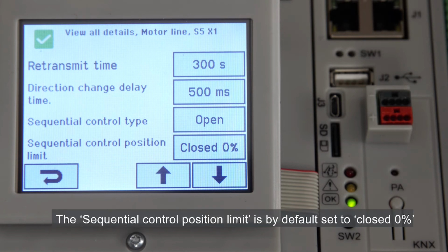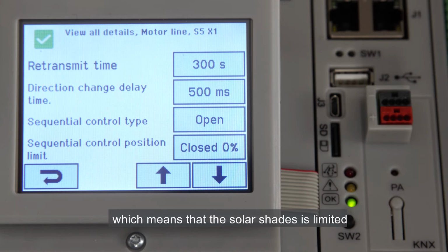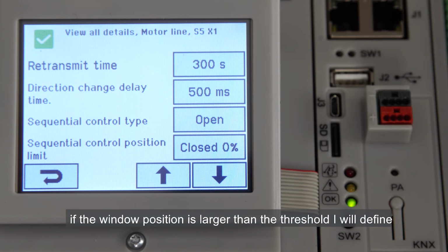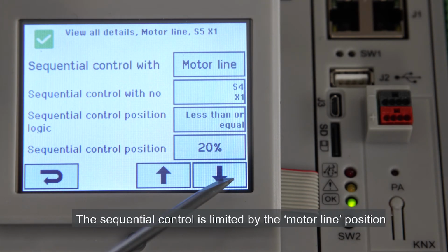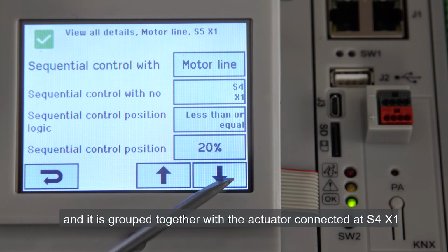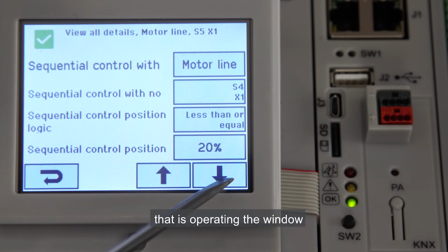The sequential control position limit is by default set to closed 0%, which means that the solar shades is limited to stay completely up, that is not covering the window, if the window position is larger than the threshold I'll define. The sequential control is limited by the motor line position, and it is grouped together with the actuator connected at S4X1 that is operating the window. So it's limited by the position of S4X1.